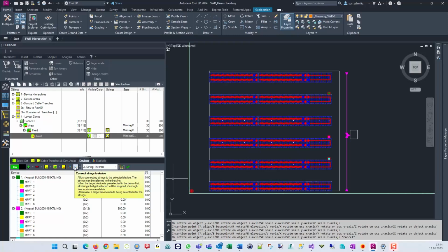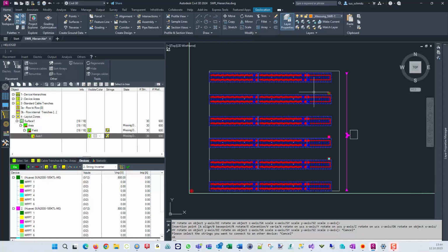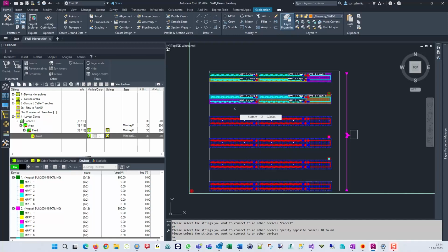Group selections consider the automatic placement criteria that strings from different module rows should not get connected to the same MPPT, and also the default order for connecting strings. We can influence the connection order by selecting smaller string groups and confirming the connection for the current selection with right-click. So we might need a different string design like the automatic one.